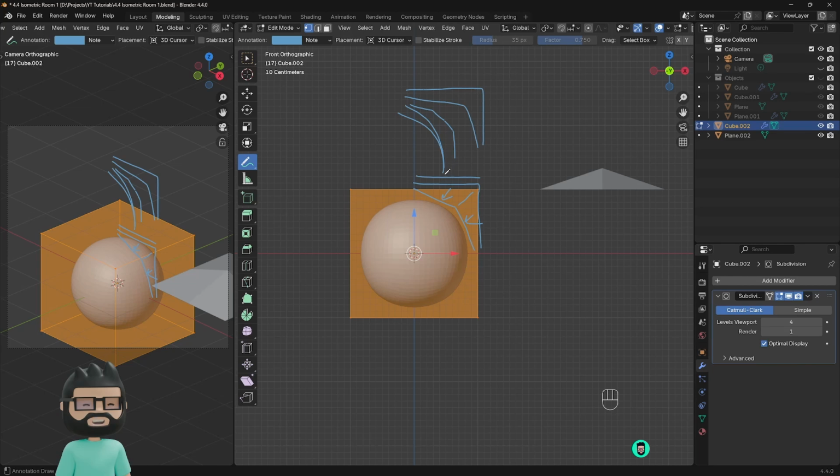So if we keep adding, it keeps on increasing the face count by 4 times. So you want to keep the subdivision level to 2 or 3 to keep the surfaces smooth and not blow up your system. It's really heavy on the system. That is what I mean to say.